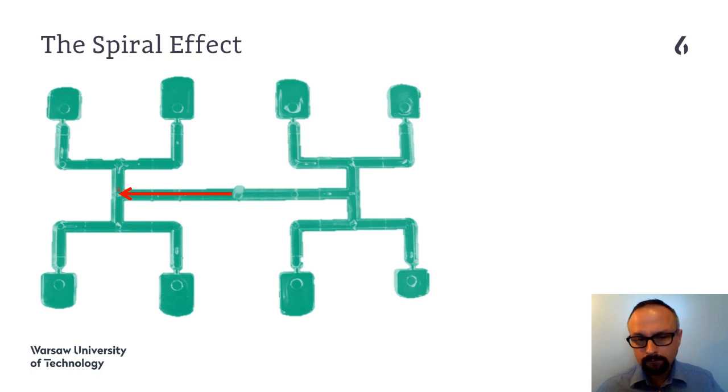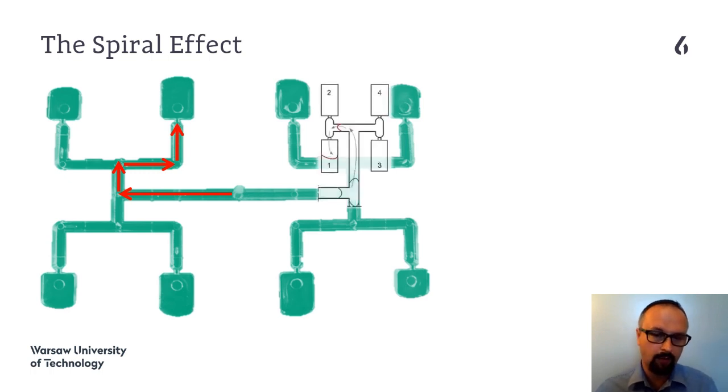If we draw the flow path along which the polymer flows fastest, has the greatest velocity, and we have a mold with more than 8 cavities, for example a 16 cavity one like this, we'll see that the path of the fastest flow tends to draw a spiral, a curve that is somehow similar to a spiral. That's the reason it is often called the whole mold filling imbalance phenomenon. It is also called a spiral effect.